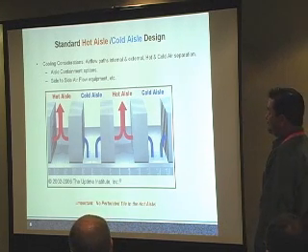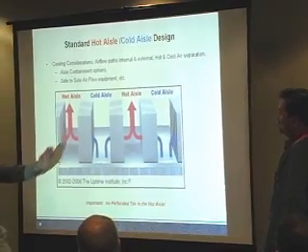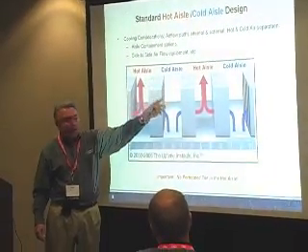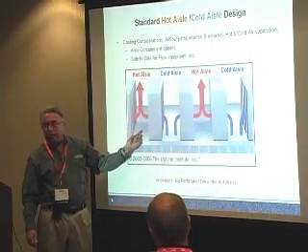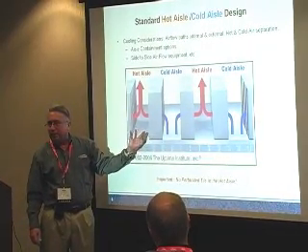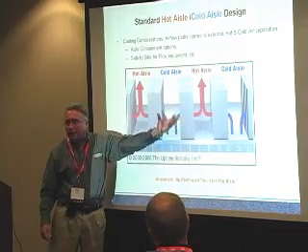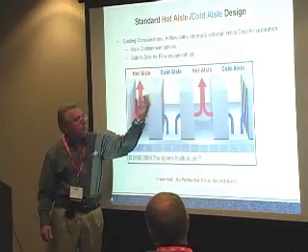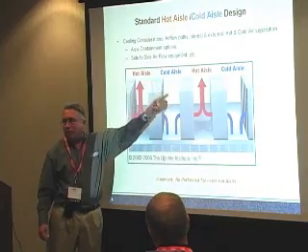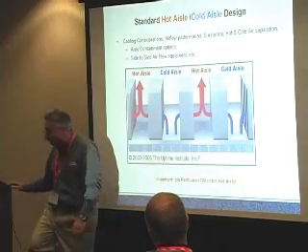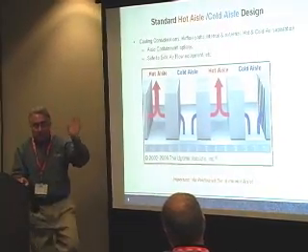Well, you may have been approached by people talking about putting walls up over here for air recirculation and things like that. First thing to do is look to see if you have air here pushing up, because if all your air is pressurized here and this has greater air pressure, then this won't come over. So take out some floor tiles, you might save yourself a ton of money buying those overhead containment doors.